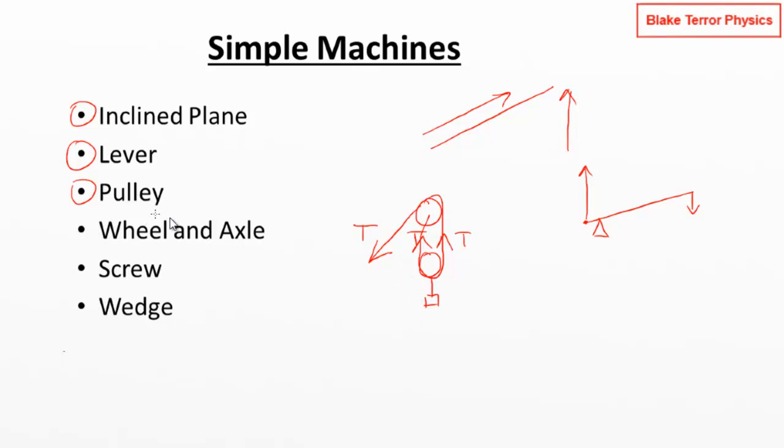Using ropes in pulleys, wheels and axles. So for stuff that we're spinning round, you might have a big wheel with a crank handle on it. You turn the big wheel round, you've got a little axle. The axle on the wheel is going round at the same speed, but we're now going to get a greater force being applied radially on this axle.